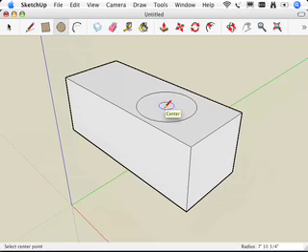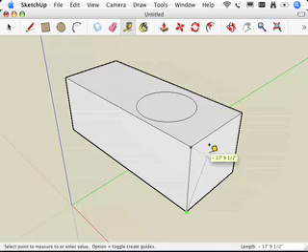That's information that's relevant to the tool that you happen to be using here in SketchUp. A really good use of the VCB is, of course, to measure things. So if I come up and get the tape measure tool, just like this, and then start measuring an edge, we'll click from here to here, you can see that that's a 17-foot 3¼ inch line, which happens to show up on the tooltip, but it's also down here in the VCB. So it's in the little yellow tooltip that appeared next to the cursor, and also down there in the VCB. I'm going to hit escape to cancel whatever I was just doing.